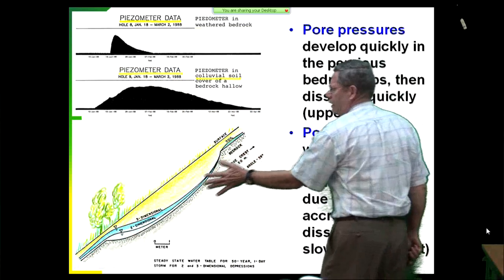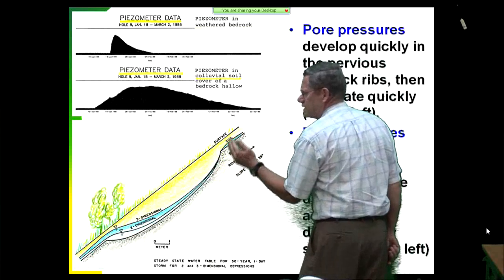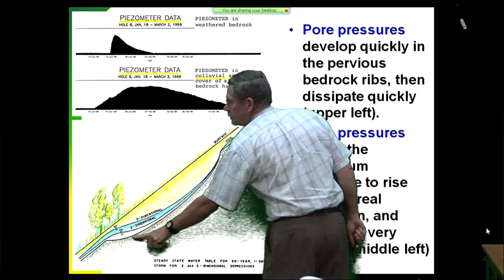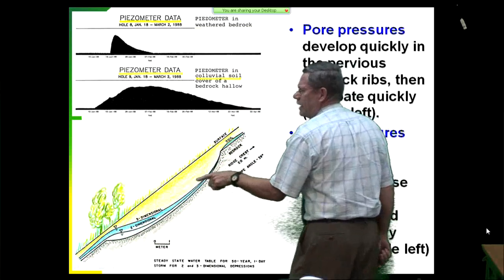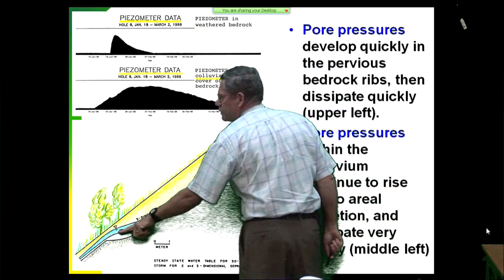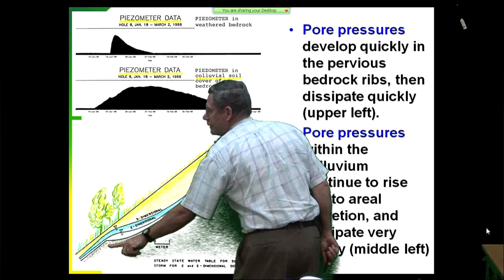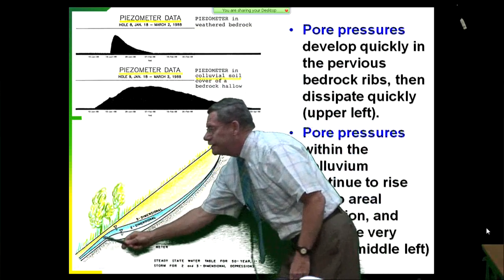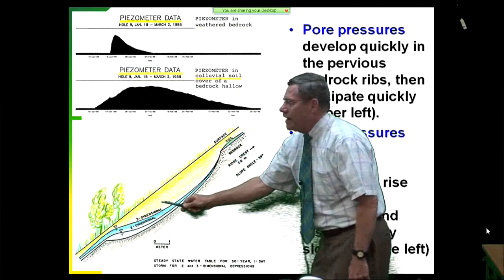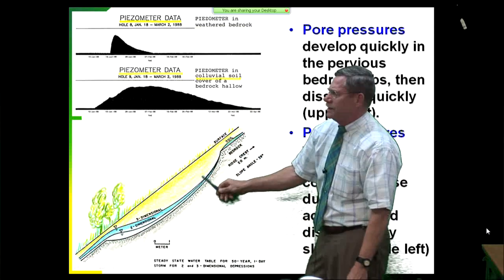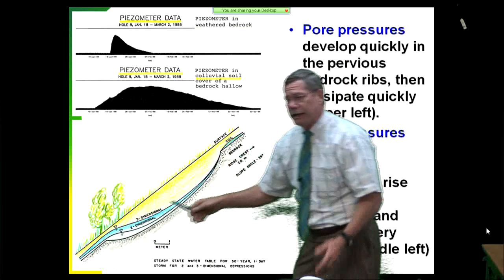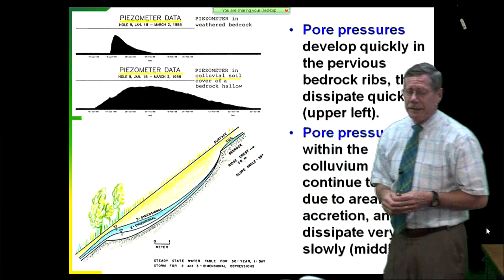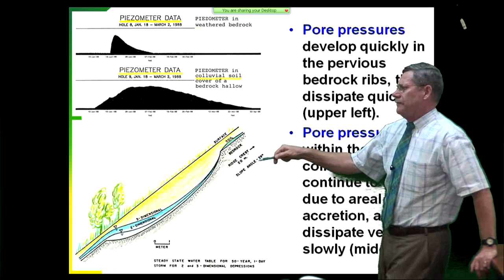Now here I am, I'm modeling it with finite elements here. Classic spoon-shaped depression. The low line is the two-dimensional model, which everybody starts with. And notice where I'm getting the accretion of pore pressure. Right down here where the pinching's occurring. Ha! Big surprise. That's where the pinching's occurring. Now, if I model it three-dimensional, look at what a difference it makes. I double the pore pressures by modeling it as it really is in 3 dimensions. So this is where the value of finite elements is.